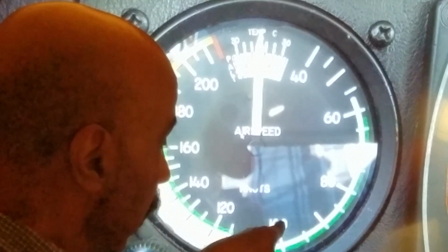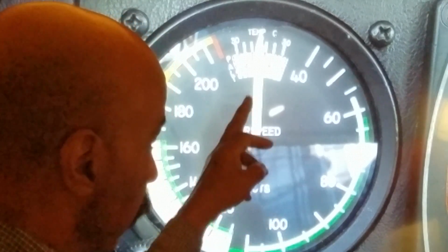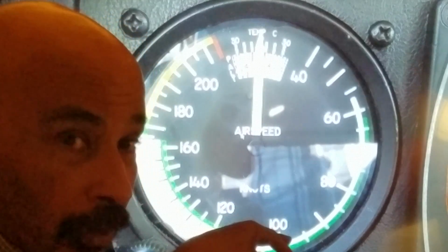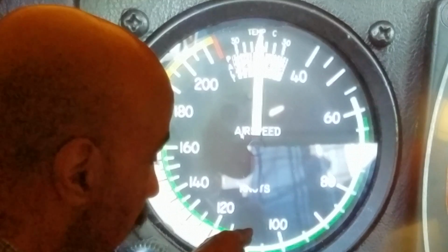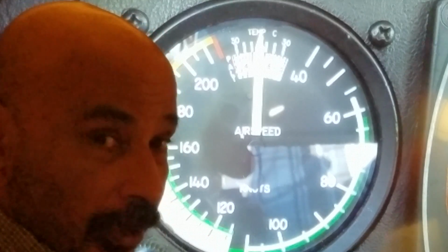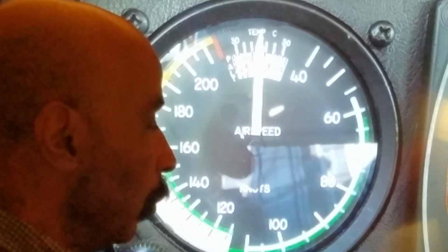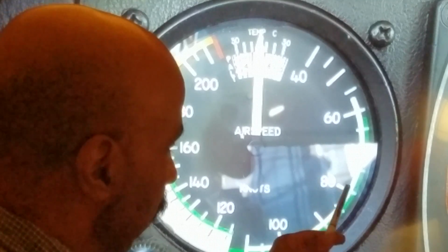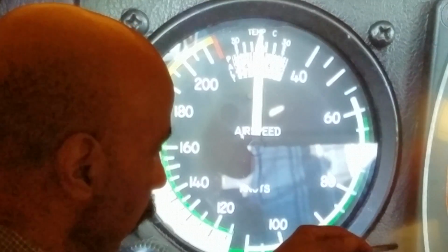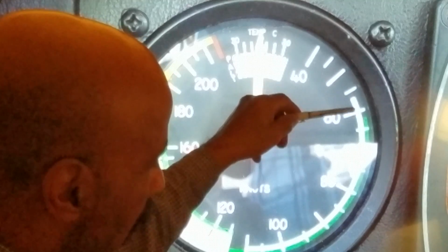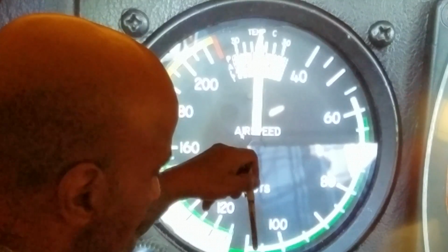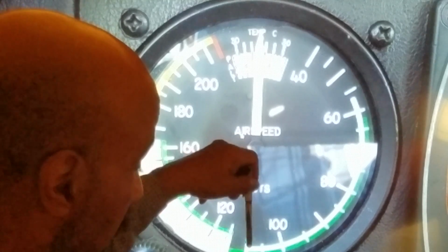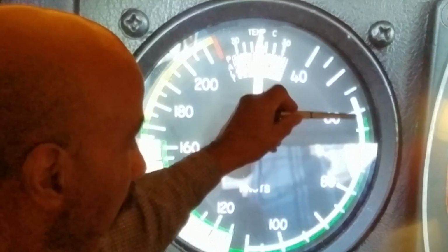This aircraft, if it were indicating 100 knots, would probably be flying, if you were going in miles per hour, slightly above that at about 110 miles per hour. And we'll look at those conversions later as we get more deeply into the course. Again, the white arc is the flap operating range. Do not extend the flaps when you're going faster than the top end of that white arc.